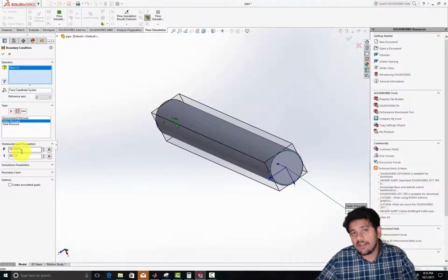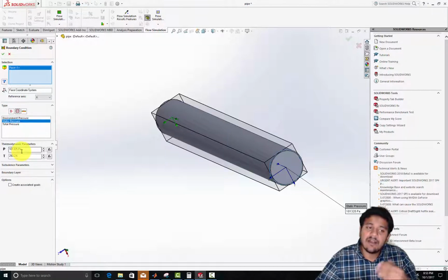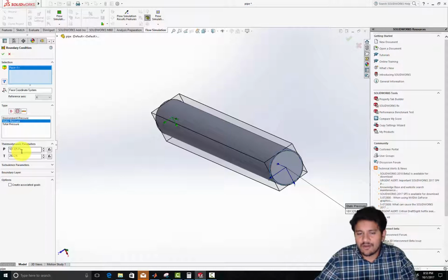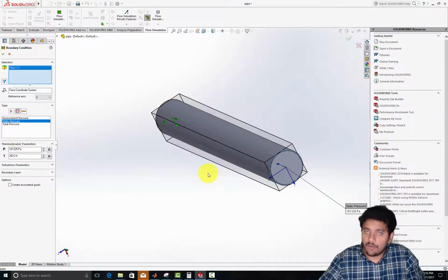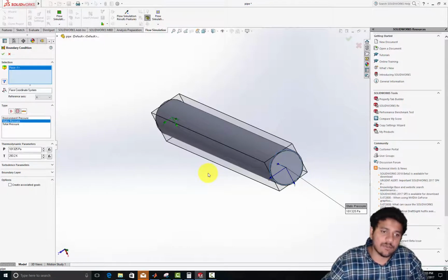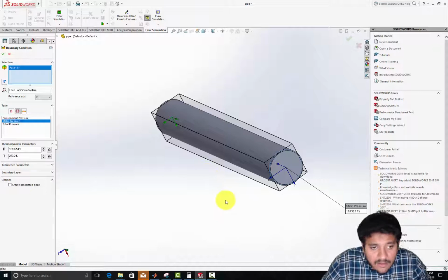This is what you call the solution not converging. And typically the solution is not converging because the boundary conditions are wrong, or sometimes it has to do with your geometry. So in this case, you can see that I'm choosing a particular combination of boundary conditions. I'm using mass flow at the inlet and a static outlet. When I say static outlet, at the outlet I'm providing a static pressure boundary condition. Okay, so that looks good.